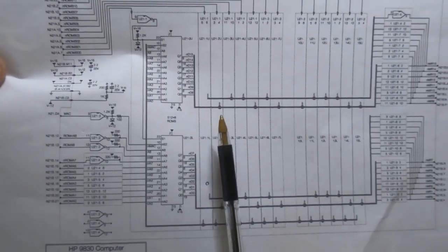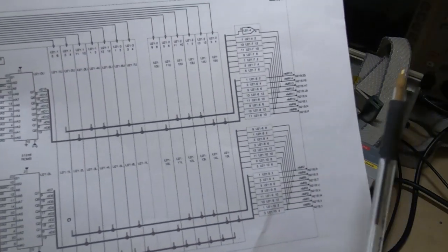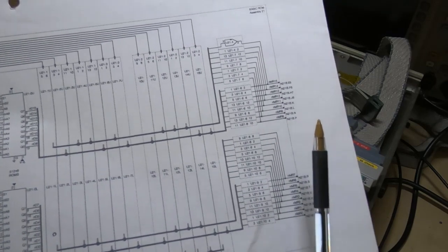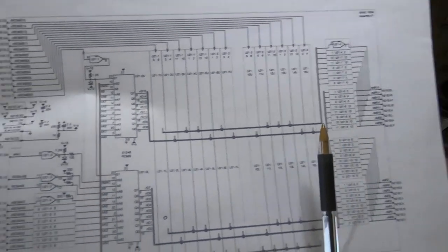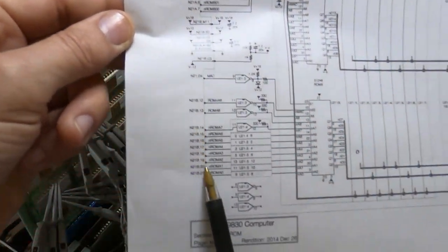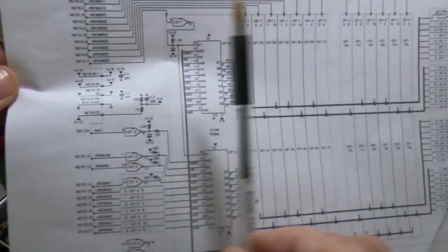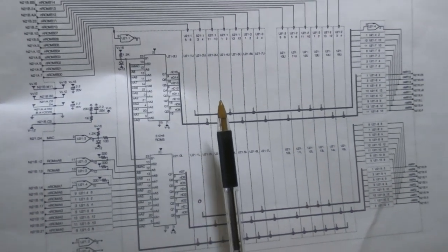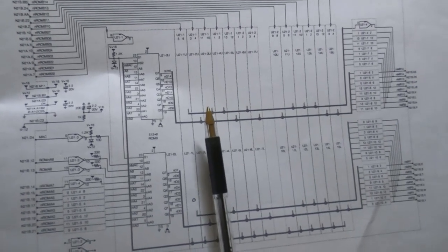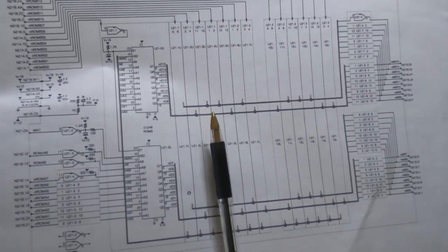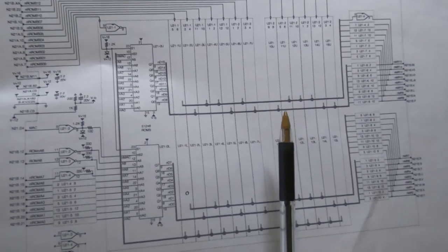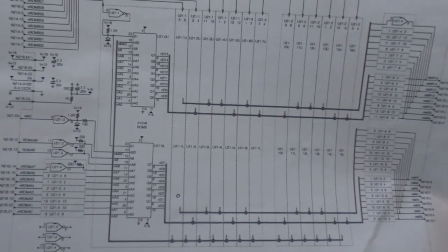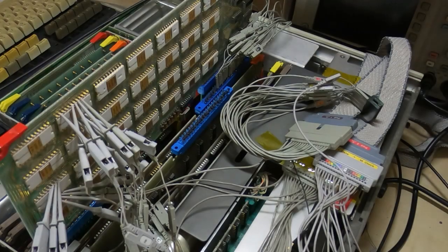So what I decided to do is investigate what was going on, so I hooked up the logic analyzer to the output of the T register and the output of the M register. The output of the M register is what determines the address that we're trying to read from, and those two should give me the input and output effectively of this ROM card. So I triggered on various addresses and started going through the code. I'll show you what I'm finding and then go from there. So I'll move the camera to look at the analyzer and we'll capture some data.